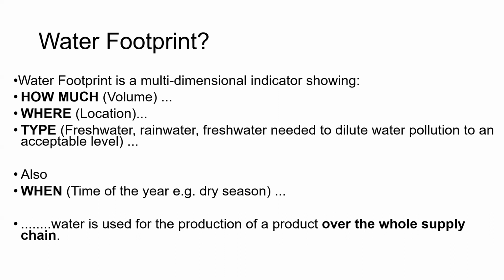And for this reason, the industry should install a flow meter. And also, if they are eligible or they have the CGWA permission, a piezometer will also be there within 50 meters of the borewell. We have to verify all these things from the site visit: whether they are complying, whether the piezometer has been installed within 50 meters, and whether the flow meter has been installed, is running, and is calibrated. Everything we have to check. We also need some tools to measure, which we will discuss later on, such as how to conduct the audit, how to prepare the water budgeting, and this water footprint.